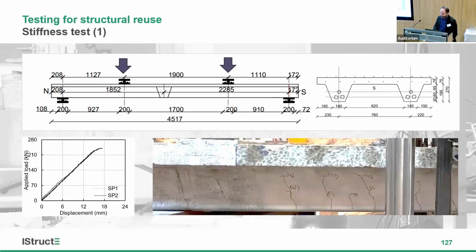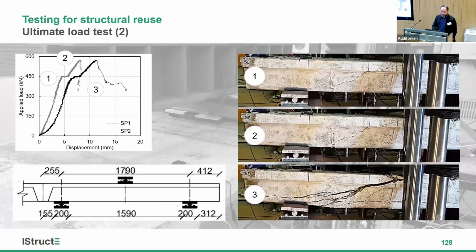It was very stiff. And this is very useful only to get the stiffness of the slab rather than anything else. We've done the 2 tests on half of the spans, and on the diagram on the left there are 2 load-displacement curves. One shows the displacement of one of the ribs, and the other side of the ribs. The black curve tells us that there is a bedding-in effect, and this tells us that the bottom side of the slab was not perfectly smooth.